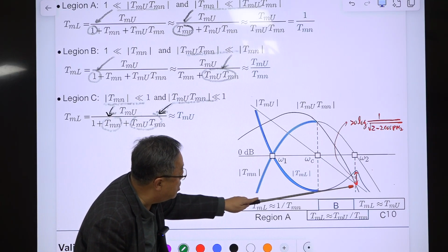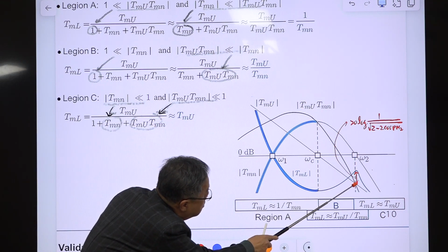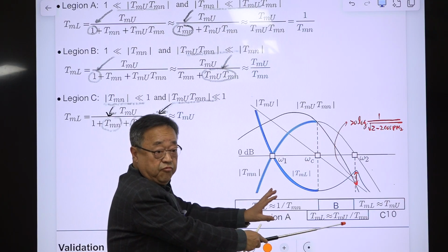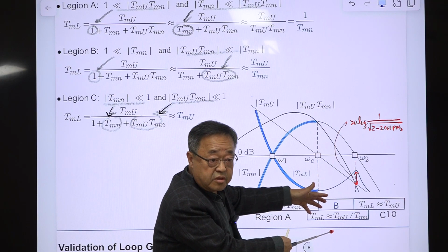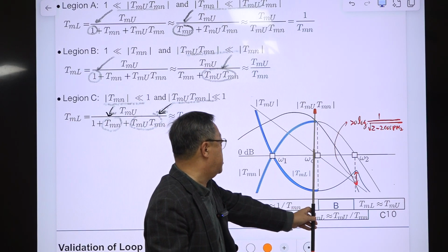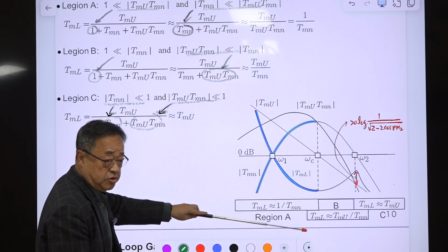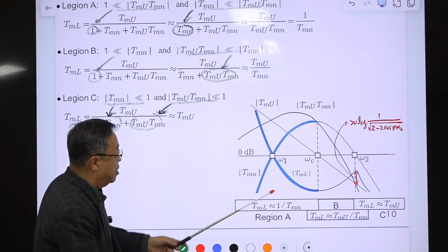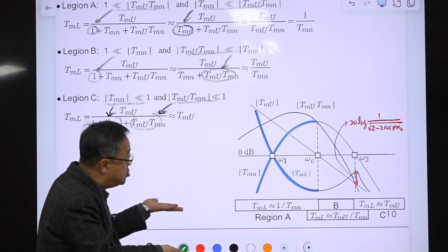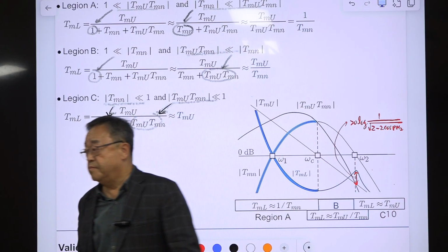So at this frequency, according to this, it should land at this point, but there is some peaking here, okay? We go over this in the next slide. So at this frequency, this relation is valid, okay? This is very good, extremely good. And the phase margin is determined at this point. Gain margin is determined somewhere, and crossover frequency is determined at this point.